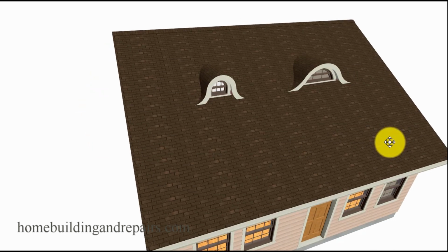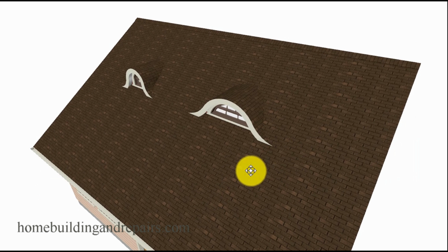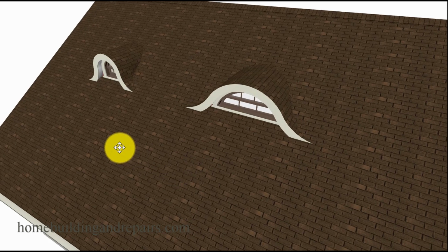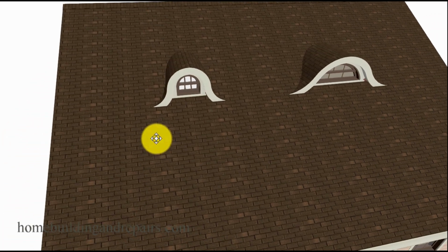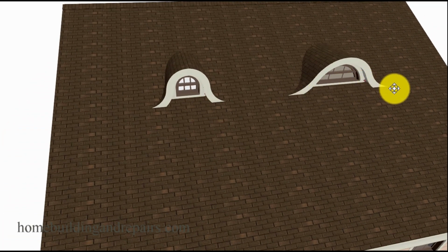Now the shed roofs are a little easier to build. These will be a lot harder to build, and are usually referred to as an eyebrow type of roof dormer, and they can come in different widths. I believe this is about 8 foot, and you could go 10 foot, and then of course you could lower this or raise it up, and that would give you a different shape here. The taller and wider they are, the more light they're going to allow in. And they are going to be a little easier to build, wrapping the shingles around something like this, than when you create some type of barrel.